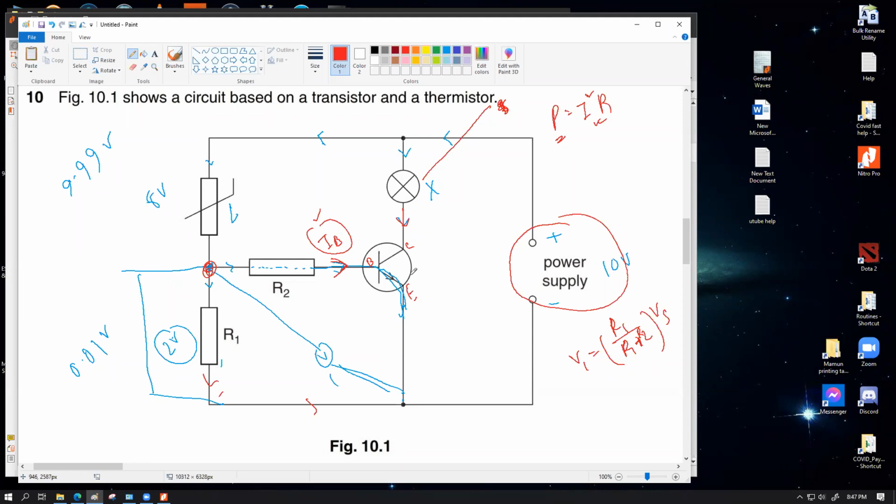Allowing 1 ampere through here, if you have a magnification factor of 100 for the transistor, can allow up to 100 ampere through this branch. But that does not mean 100 ampere will by default generate within the transistor. No, you have to have the means and path to make 100 ampere flow through. And then if you allow 1 ampere through here, then the 100 ampere can pass through.